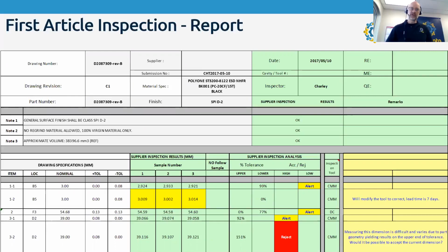We will also look at the drawing, the slide before, and if you have a high tolerance area, we may want to discuss that. We are going to have an inspection plan to make sure that we can inspect like you expect, and that may involve some negotiation on what type of tool and how we're going to set the thing up and how we're going to fixture it to hold it so that we can measure it.